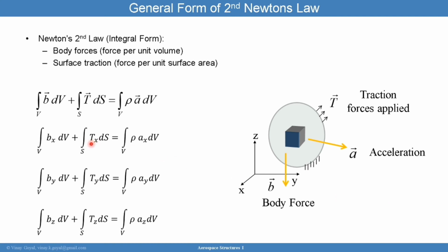I have the tractions applied, I have the body forces applied, and the acceleration supplied. But that doesn't help me determine when the structure breaks. So I have to now somehow tackle this problem. And one area where I can examine carefully is the traction force T. Traction force T can be related to stresses inside the body.